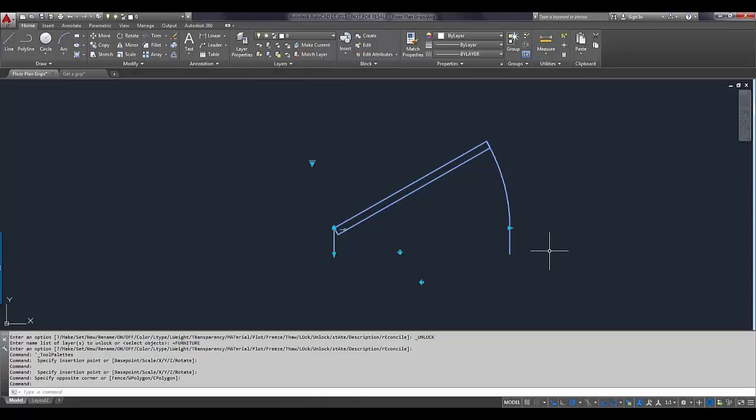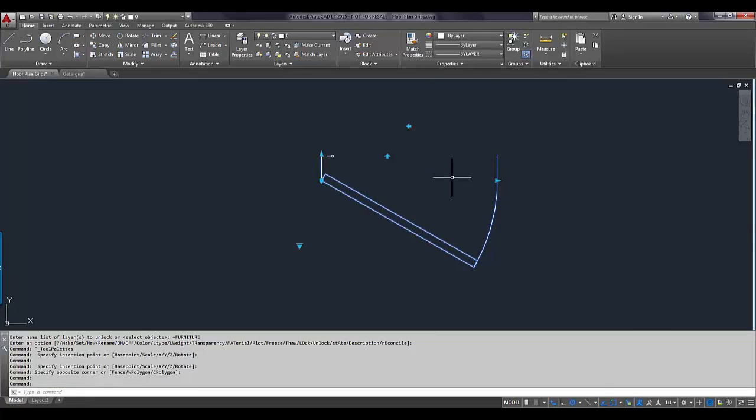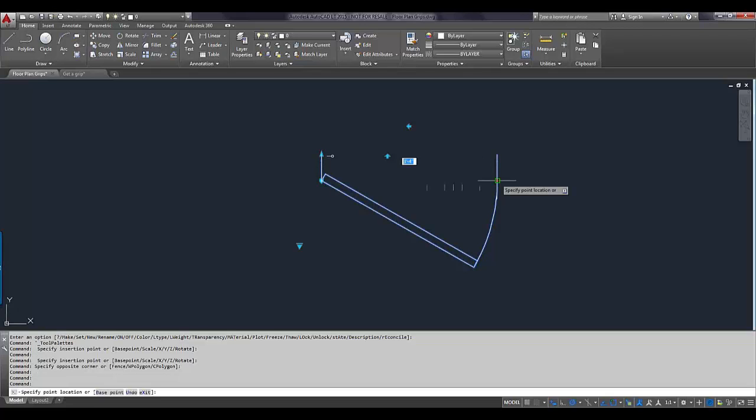Yeah, since we do have some extra time, sure. There are different grips here. We have what is called a flip grip, and that changes the direction. This grip here allows me to control specific sizes for the door itself. Notice that it's jumping between increments of, in this case, 2 foot, 2 foot 4, 2 foot 6, 2 foot 8. Yeah, and it can go larger than that. It's just for this particular block. It all depends what you want to put into that block, really.